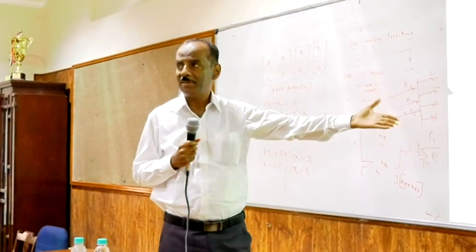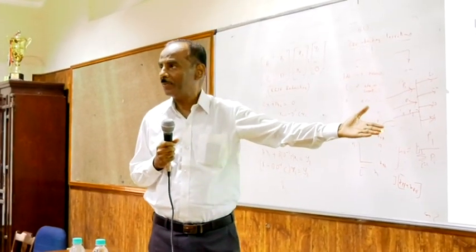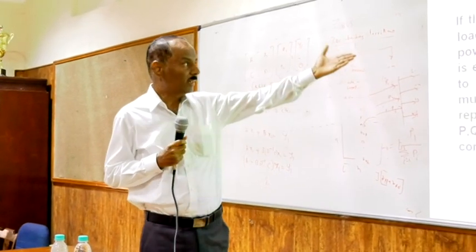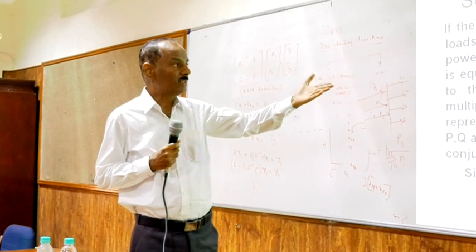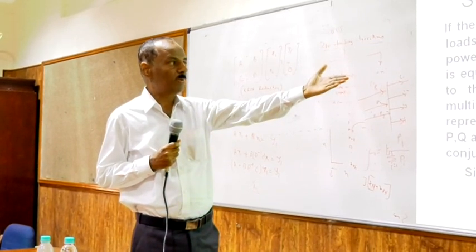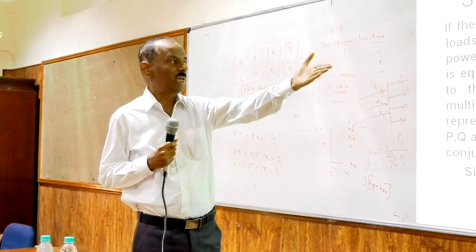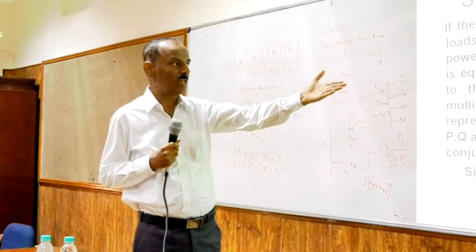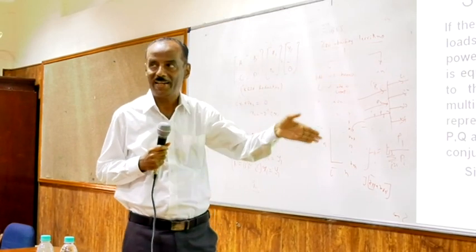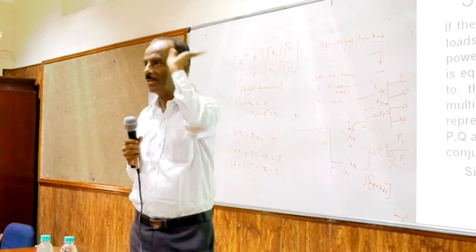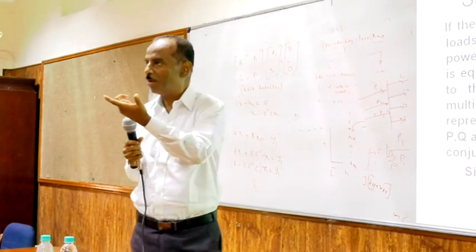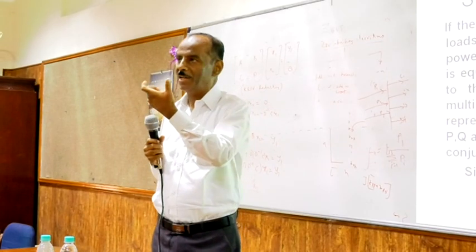So this is actually just like that. I try to find out this. You see that m sources are there, n loads are there. What is the power shared by the source i with the jth load? Sij is equal to the ratio of the source current Ii, of the source you are considering, to the total current. That's all. See how simple the algorithm is.